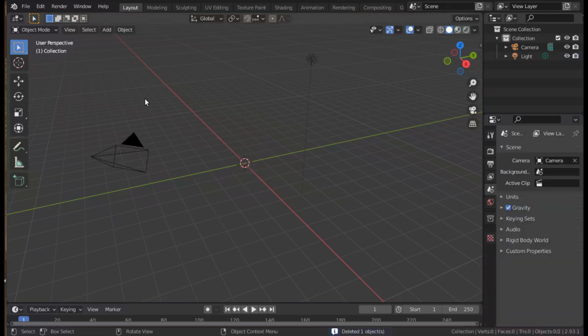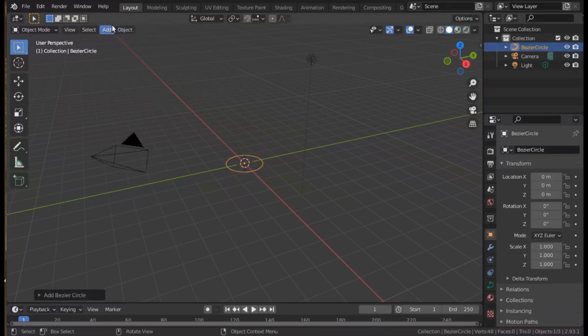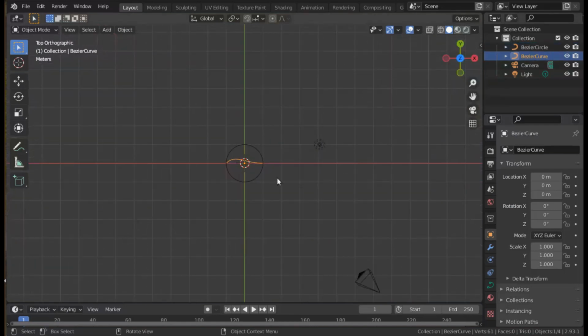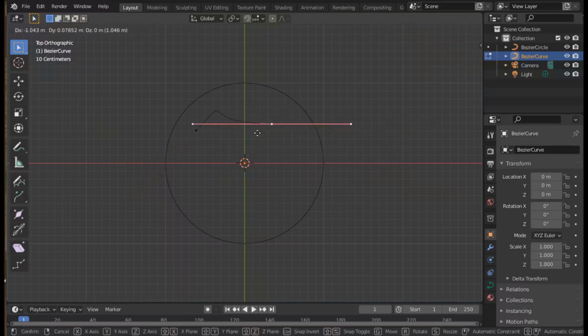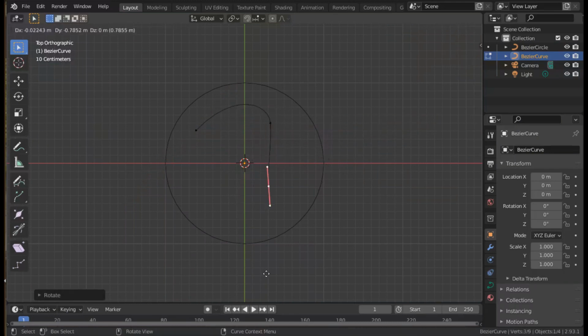In this exercise we're going to look at using curves to make 3D objects. We've got a Bezier circle to extrude around. We're going to add a special shaped bevel which we're constructing from a Bezier curve.